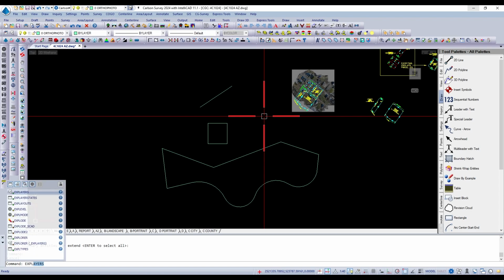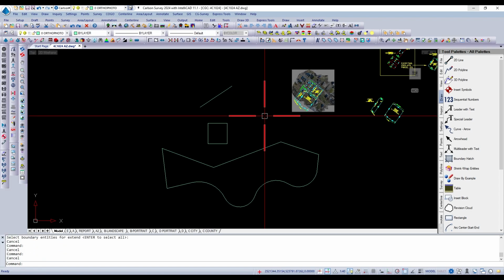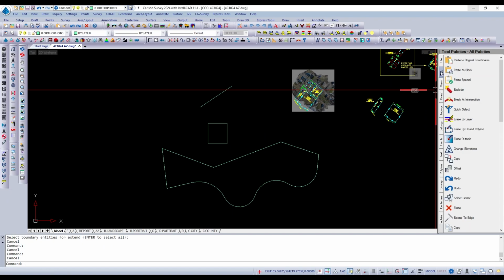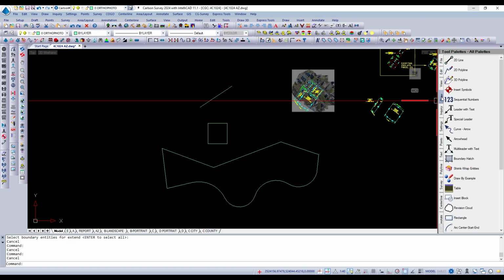You can type it in, but over here on the edit tab on what's called the palettes, I like to use this. We have many of the same commands that we've used previously. If we go to draw, you've got line, 2D line, etc., 3D line. You can drill down through here and find all kinds of commands. These palettes can be edited to include different commands. You can rearrange the palette by dragging a command up or down if you don't like where it is.